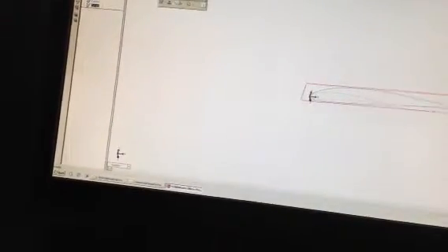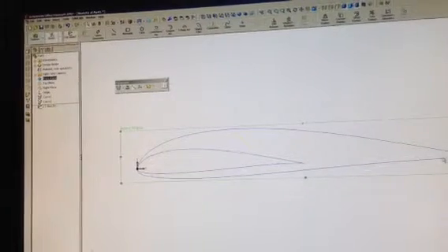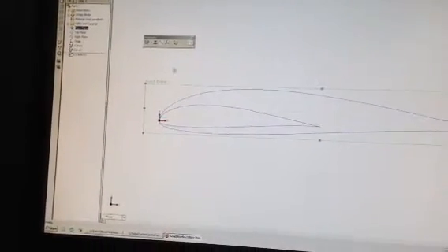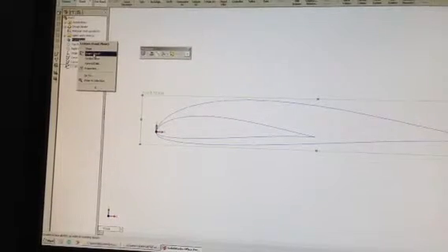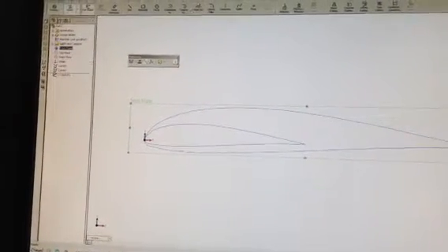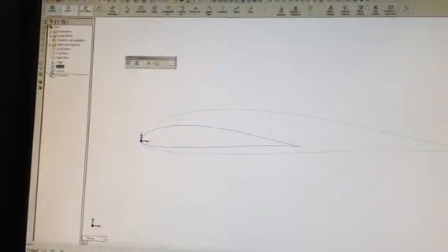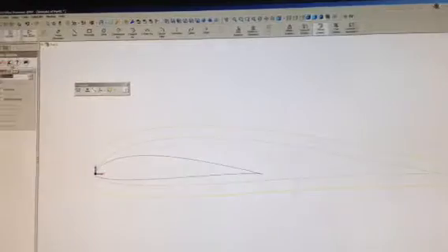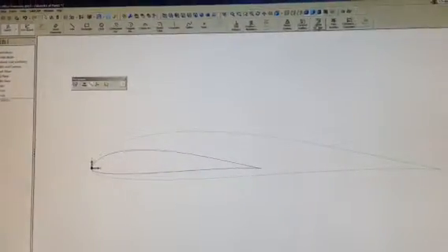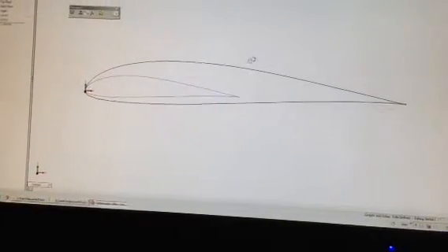So what I want to do is on the front plane I'm going to insert a sketch. Okay, I've already got that curve, that's my outline, so I need to create a sketch of the outline. So what I do is right click, insert sketch, which I've done, it's there, and I will select the big curve and click convert entities. That's the wrong tool, I've pressed offset, cancel that. I'm going to convert entities, so this becomes black. That means there's a sketch that's of the same curve outline as the curve on my front plane.